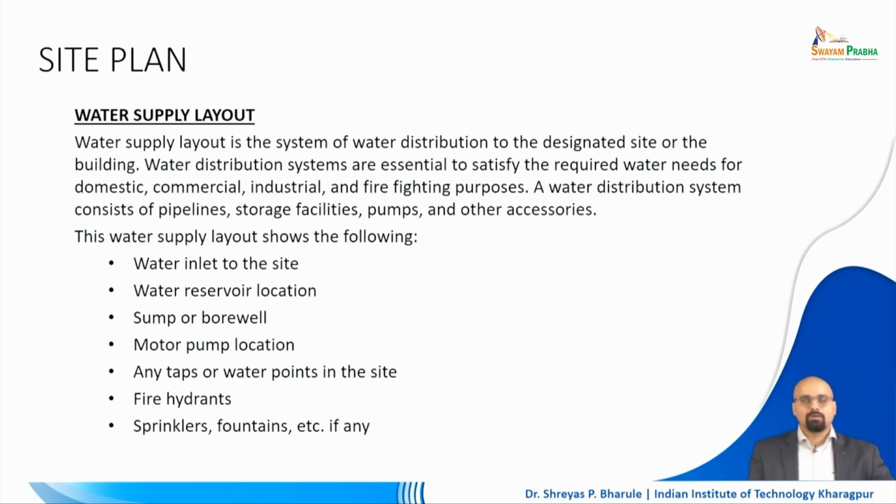Location of your water extraction pumps, or if there is an underground water supply, a borewell location, so your pump location, how you will be dropping down the pump, if there is a well, a water well around there, how that is connected to your water supply, all of that is to be drawn on the drawings, right.